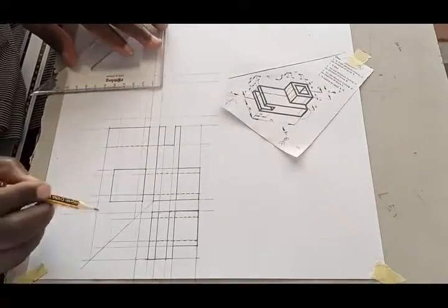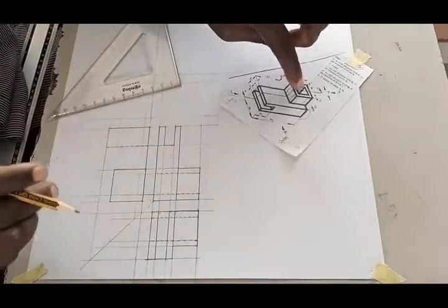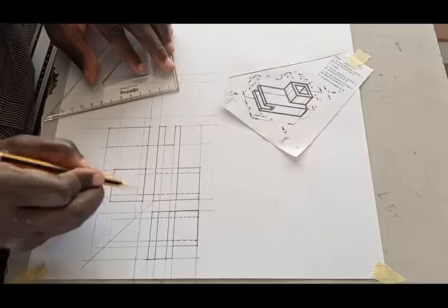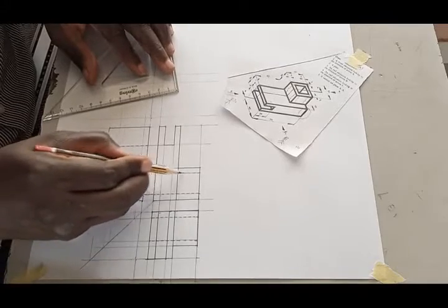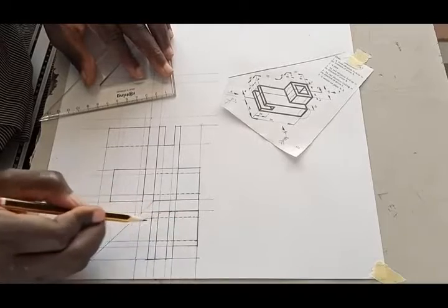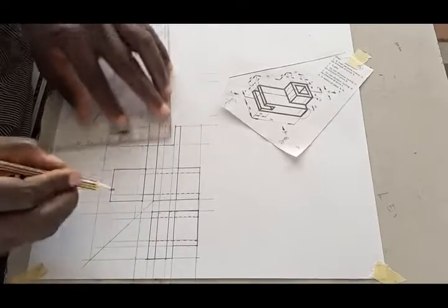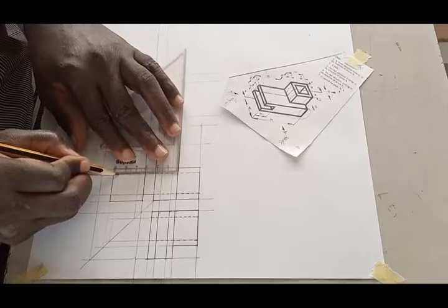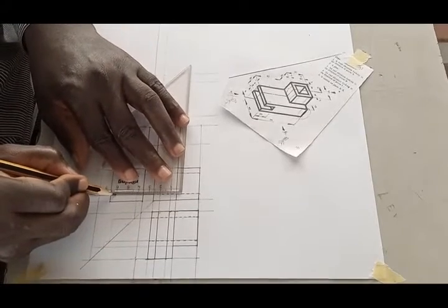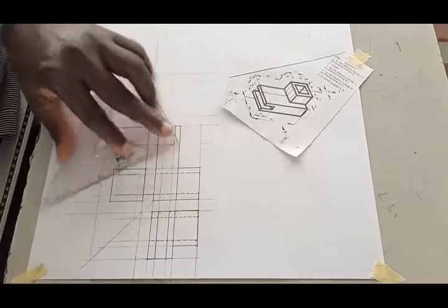Like that. Now, coming back to the hole again, the box at the top, you can see that there's a hole there. You can see the hidden line. These two hidden lines represent this one and this one. And these other ones represent this one and this one. But this time around, because you are looking at it from the top, you can see it. So it will be a thick line. They give you thick lines.